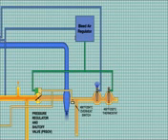If system temperature reaches 450 degrees Fahrenheit, the 450 sensor will open. This reduces the control air to the PRSOV, causing it to move toward the close position. This reduces the amount of bleed air flowing through the pre-cooler. With less hot air flowing through the pre-cooler, it can reduce the temperature of that air more effectively.